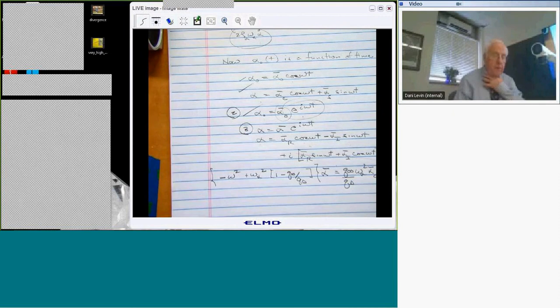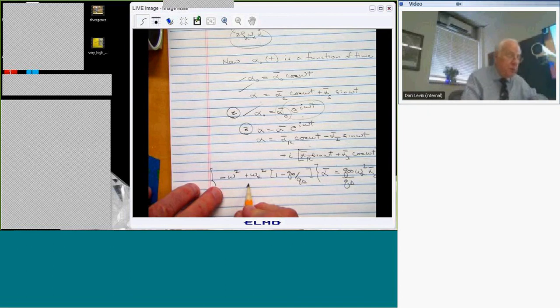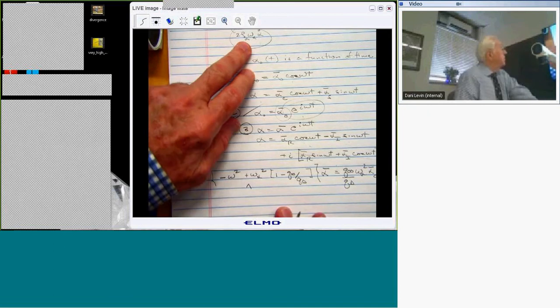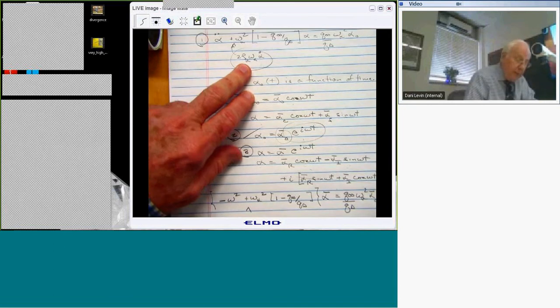And just to remind you, if I want to put in structural damping, that's this term, then that will add 2 zeta alpha omega alpha times i omega, because an alpha dot generates an i omega.